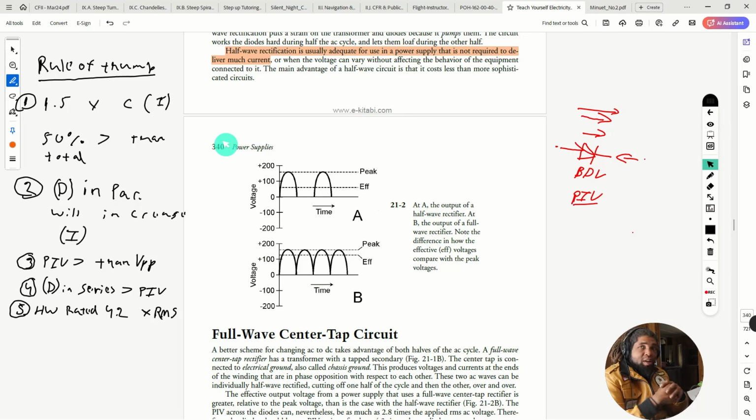If they're using what's called a fixed bias for the output tubes, they'll often use a half-wave rectifier for the negative voltage that needs to be placed on the grid of the power tube.